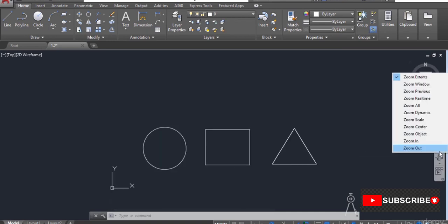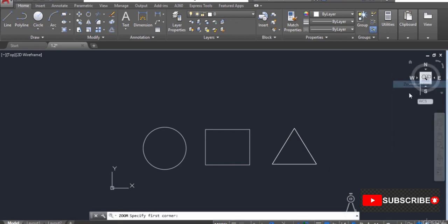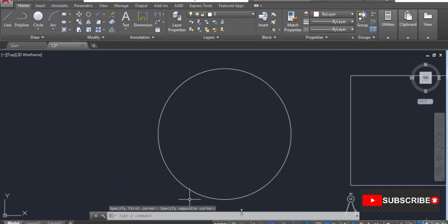We also have other options like zoom window, which can be used for zooming on a particular object. For example, let's say that we want to zoom into this circle. Simply make a window around the circle, and the circle will be brought into perspective. It will be zoomed in the current workspace.